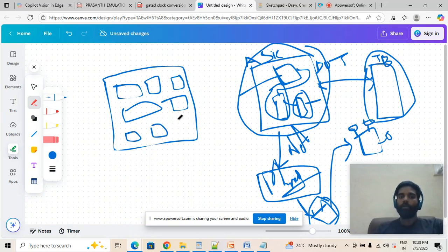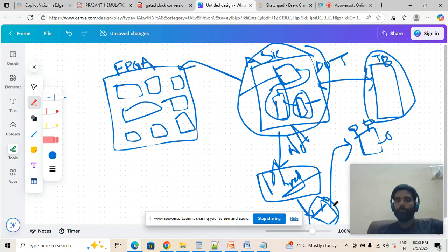Now I have one idea. Fine, let me take my ASIC RTL after verifying it in simulation test cases, and take it into the real hardware, which is called FPGA hardware, right? So before I go for my further process, my backend implementation and then the real silicon bring-up activity, let me take this RTL and place it on FPGA. Placing this ASIC RTL into FPGA comes with a few challenges. My ASIC RTL is written mainly for ASIC purposes.